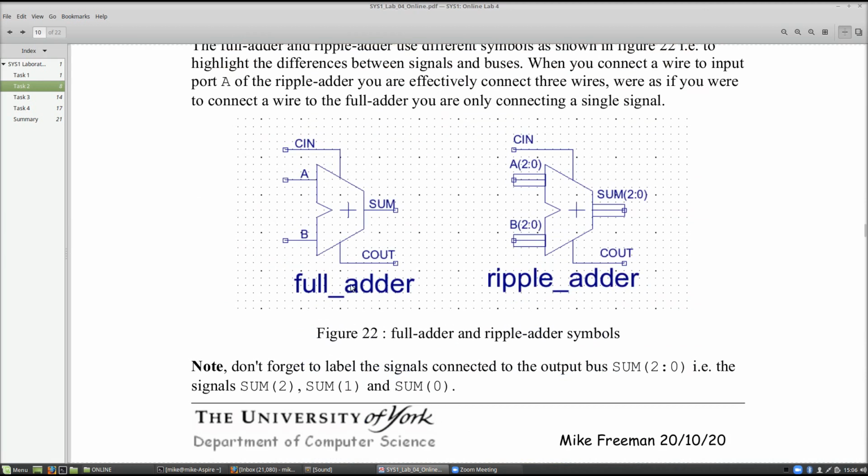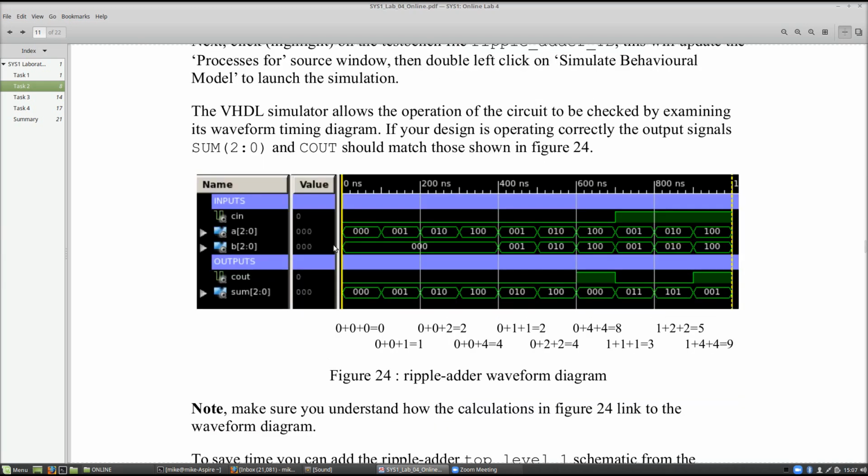And again just to hammer that one home, the difference between individual pins coming in, so signals, 1s and 0s, and again buses. Now we have components that can process bigger words. And again we can test that one in iSim, so do make sure you're happy about the difference between signals coming in and buses coming in.